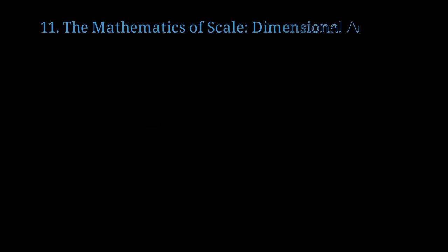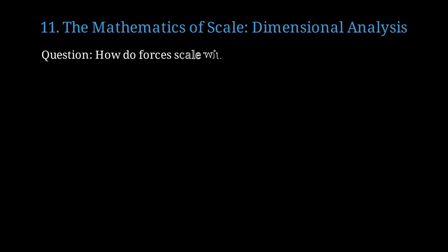Let's dive deeper into the mathematics that governs scaling behavior. Critical question: how exactly do different forces scale as we change the size of our system? Volume-based forces, like gravity and inertia, scale with length cubed. Surface-based forces like viscosity and pressure scale with length squared. Line forces like surface tension scale linearly with length.